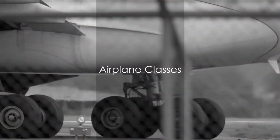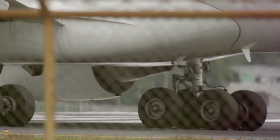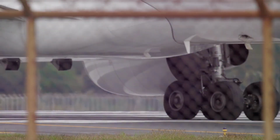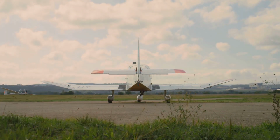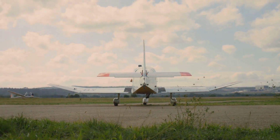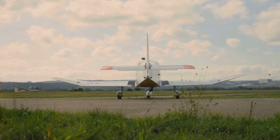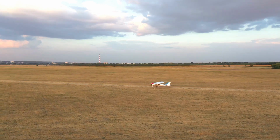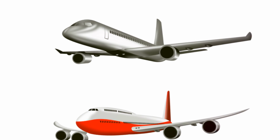Airplanes can also be classified into different classes. Each class is distinguished by specific characteristics such as the number of engines, the type of propulsion, passenger capacity, and the maximum takeoff weight. Let's start with Class A. This class includes multi-engine turbo airplanes, either jet or propeller-driven, that can carry more than 10 passengers and have a weight exceeding 5,700 kilograms. This category is defined by the European Union Aviation Safety Agency, or EASA, under its CS25 regulations.